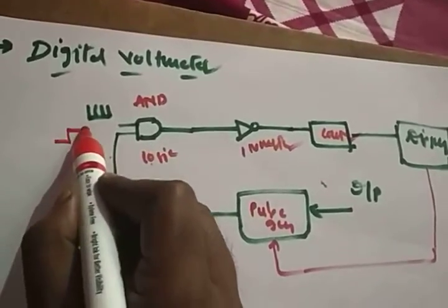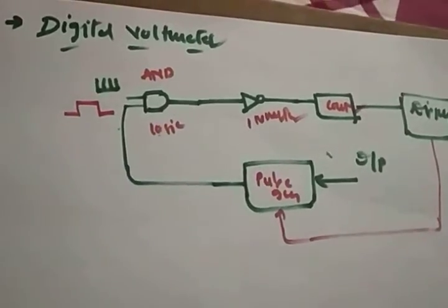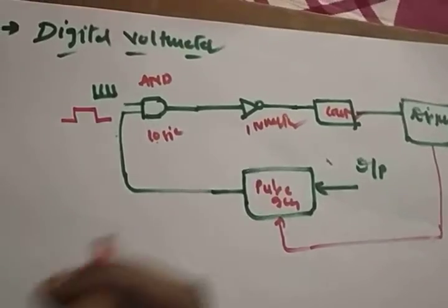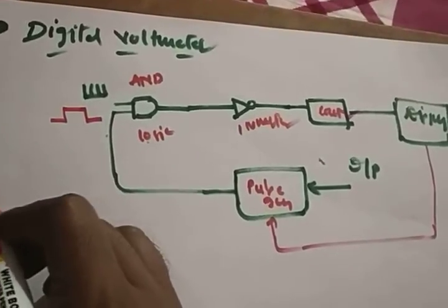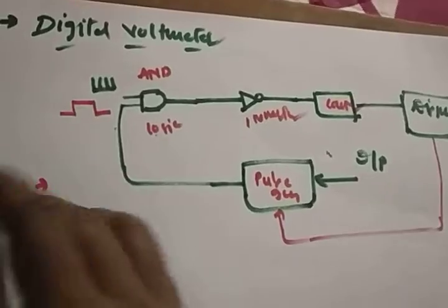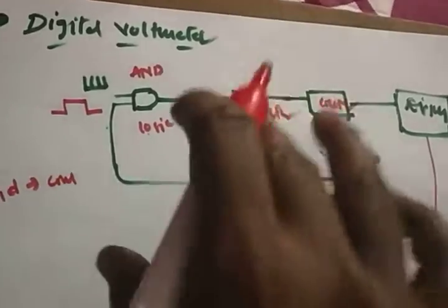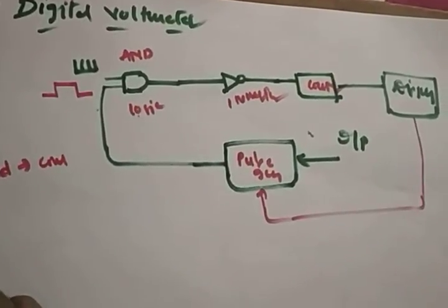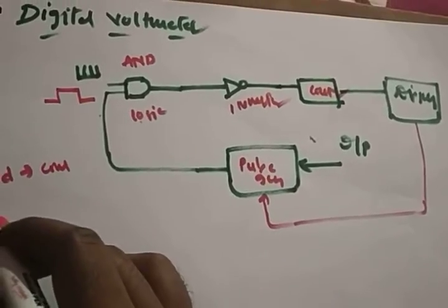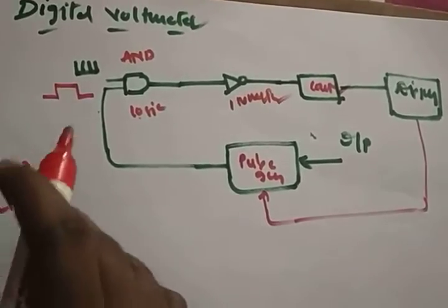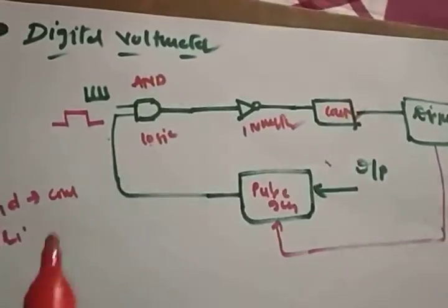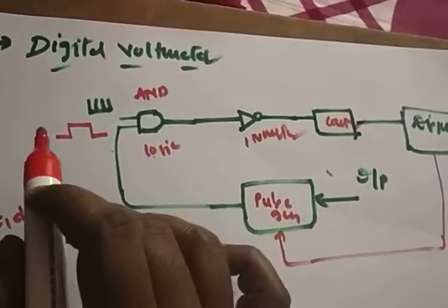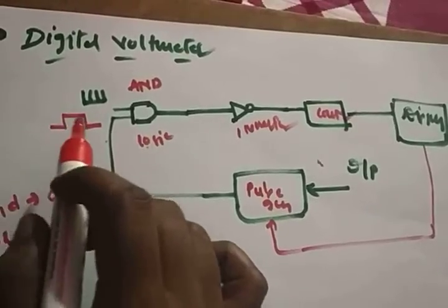The width and the frequency are controlled by a digital circuit in the pulse generator, and the rise time, voltage, and fall time are controlled by the analog circuit in the pulse generator.